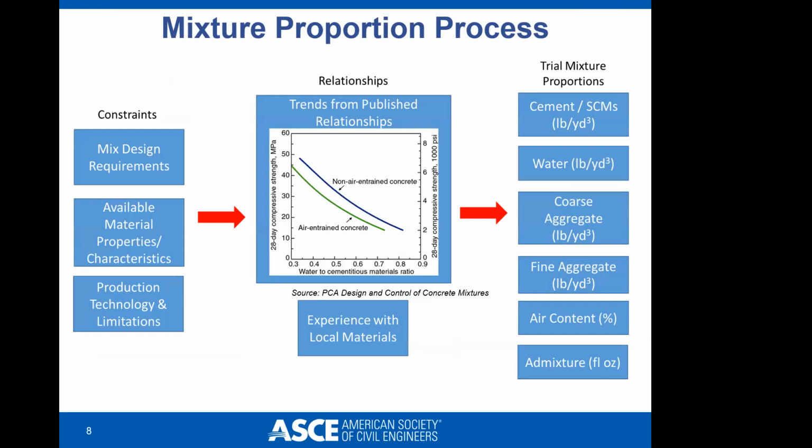The process can come generally from literature, whether it's a review of past mixed designs or looking into the textbooks online to figure out what properties you want, the constraints that you have, which are generated by the rules and regulations, obviously, the characteristics that you want, whether or not you want a mix that is below the unit weight of water or has a particular strength. Your past experience in making these mixed designs with the materials, whether it's a local shale, expanded shale or slate, or some more of the exotic materials, your general cenospheres and microspheres. And then doing your trial mix proportions.